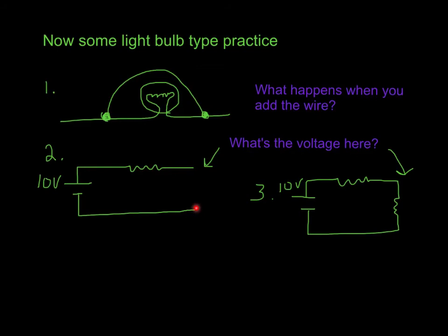If I take this resistor away, what do I measure there? 10 volts. There's no current flow through here. So there's 10 volts here and there's 10 volts here. That'll help answer this next one. What happens when I connect it with another resistor? Well, what's the voltage here? Again, pause it. If I tell you the resistor values, you might be able to get it exactly, but here it's less than 10 volts. So now we have current flowing through the circuit and some voltage dropped, so it's something less than 10. This resistor might have dropped 3, and then this one would drop 7. This resistor might have dropped 5, and this one would drop 5. Whatever it is, it's no longer 10, because now we have current flowing through and it's dissipating power. Cool stuff. Let's keep going.